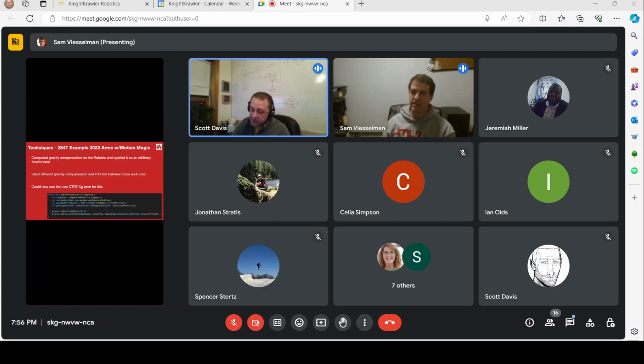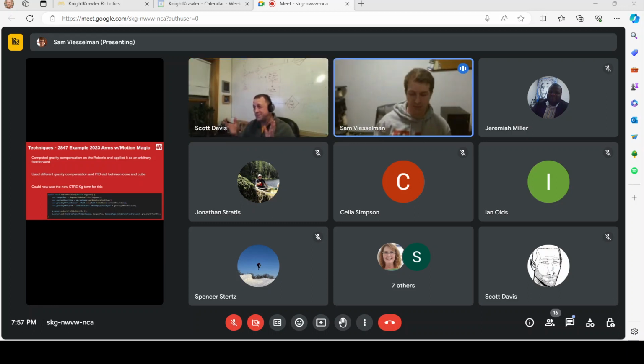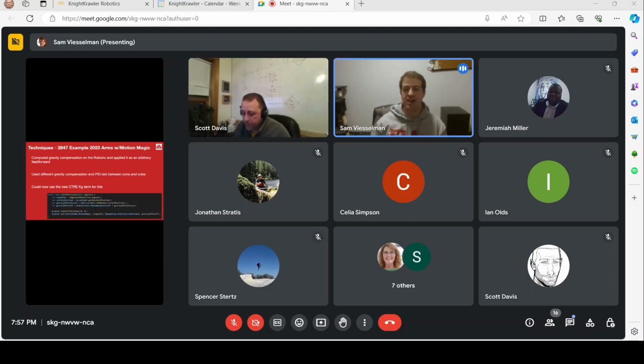So that's very helpful and interesting to me because I never really understood where to start with these numbers. And so understanding the error, and the P is a proportion, right? Another word is percentage. Is that true? You can think of it that way. It's proportional to your error. So the more error, the more it's going to do. And so in your case where it's 1, where it should be 0.005, even if you're off 0.01%, it's still going to blast 10 volts. And that's where you're going to see some of the instability when you're that high.